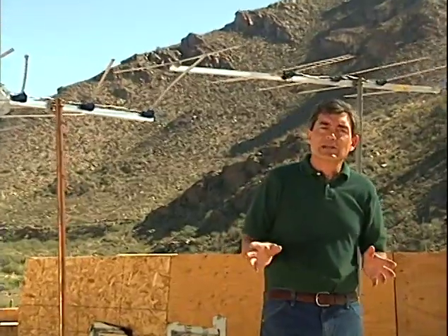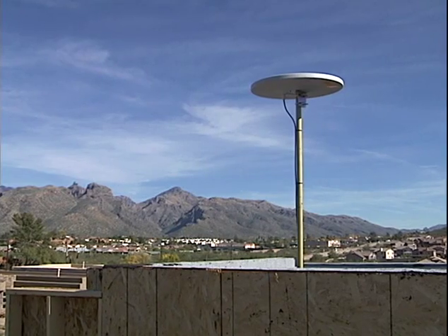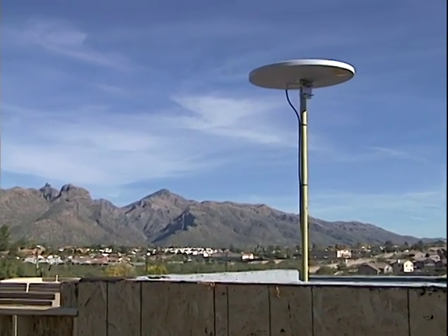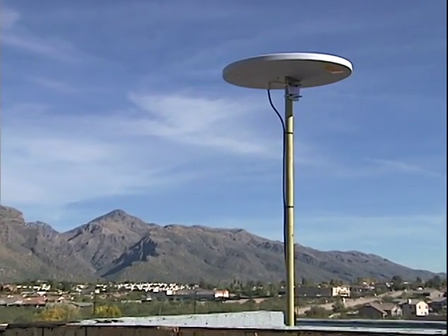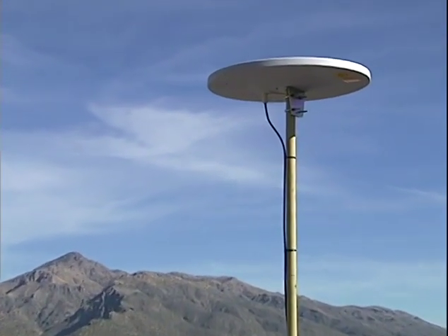Now, the other design criteria is directivity. Antennas are either non-directional, or omnidirectional as it's called, or directive. An omnidirectional antenna is designed to receive frequencies in all directions. Manufacturers make a variety of omnidirectional antennas for TV reception, typically by combining bidirectional elements or shaping the elements, such as this.